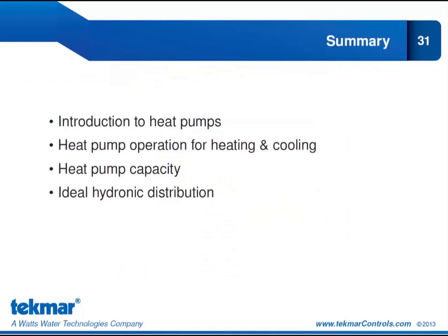In summary, in this module, we introduced you to heat pumps, the concept behind heat pumps, and we looked at how operation varies if we're in heating mode or in cooling mode through the action of the reversing valve. We looked at heat pump capacity and what the efficiency is, or the COP in heating mode, and the EER in cooling mode is.